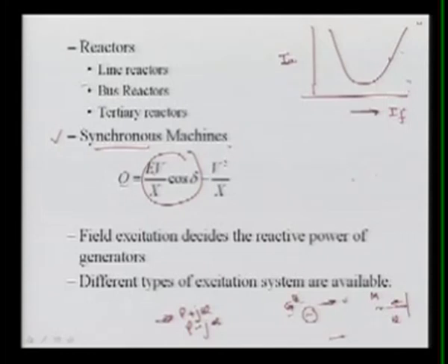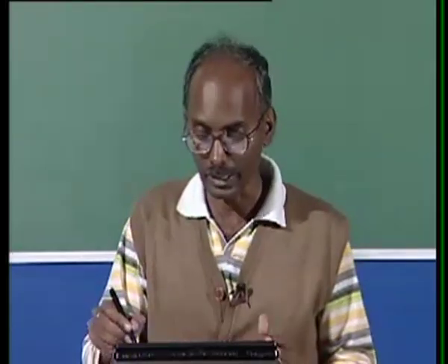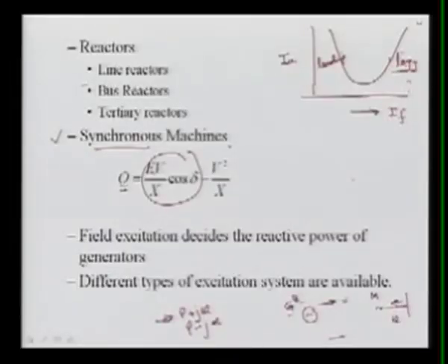So again, whether it is leading on one side or lagging on the other, this IF is directly proportional to E, as we will see later. If IF is more, meaning this component is more than this, then it is positive, and in the generator case it is called the lagging case, and this one is the leading. So we operate the generators mostly in the lagging case, no doubt. Remember, lagging for the generators.